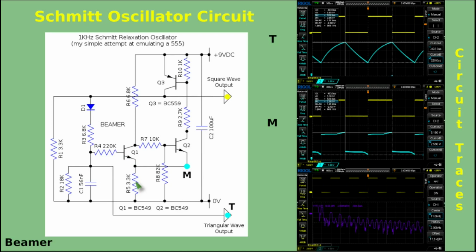Let's now go and have a look at the FFT. It is window flat top, and the frequency per division is 2 kilohertz. And we can clearly see here, this is set to more or less 1 kilohertz, that typical of a square wave, you have dominant third harmonic, fifth harmonic, seventh harmonic, ninth harmonic, and then the evens start picking up. And I don't know how true this is, but that is pretty reflective of a square wave.